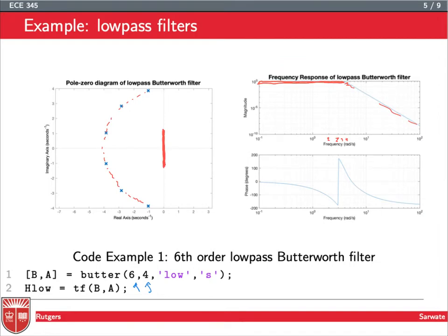So over here you can see the last pole is close to 4 at +4 and -4. So this thing is going to be flat all the way up to about here, and then it's going to start decaying after that. So if you think about the rubber sheet, you have this sort of semicircle of poles, and that's pulling the sheet up to almost a pretty much constant level between -4 and 4, and then it lets it decay off after that.